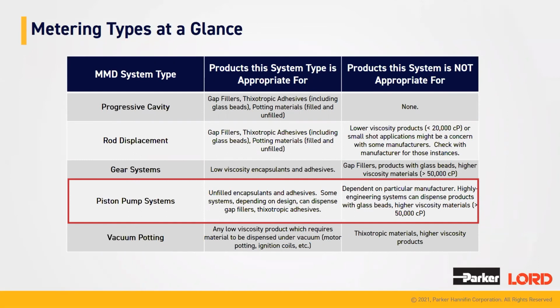Next on to the piston pump style MMD system, they're great for unfilled encapsulants and adhesives. Some systems, depending on the design, can dispense gap fillers as well as thixotropic materials. And then we do not recommend these for highly engineered systems that have glass beads or higher viscosity. So we recommend avoiding those with the piston pumps.